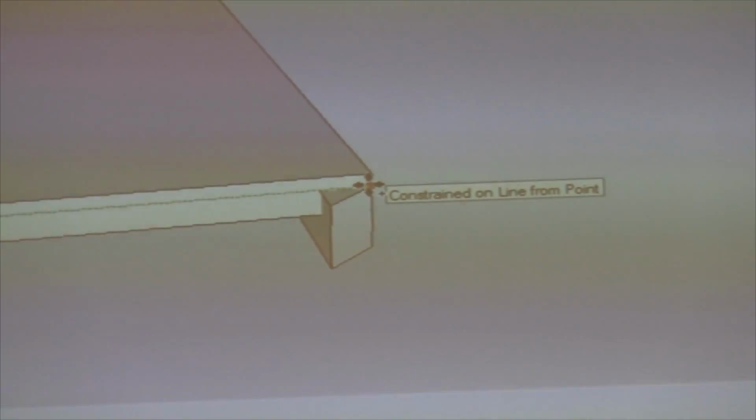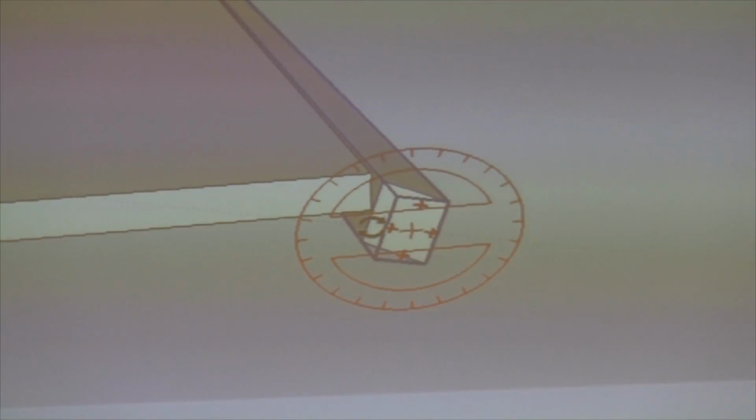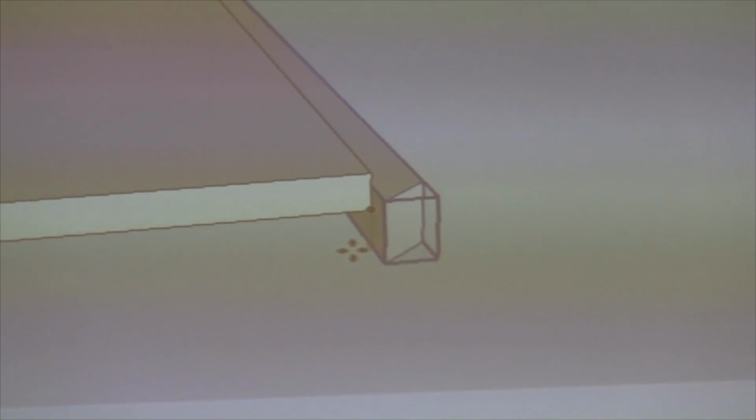We know that the front and the backs are exactly the same. So we're going to replicate this using the move copy tool. We're going to drag it to the back here, and we're going to flip it. And my favorite quick flip is that.